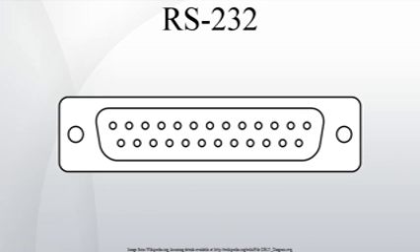Standard details. In RS-232, user data is sent as a time series of bits. Both synchronous and asynchronous transmissions are supported by the standard. In addition to the data circuits, the standard defines a number of control circuits used to manage the connection between the DTE and DCE. Each data or control circuit only operates in one direction, that is, signaling from a DTE to the attached DCE or the reverse.